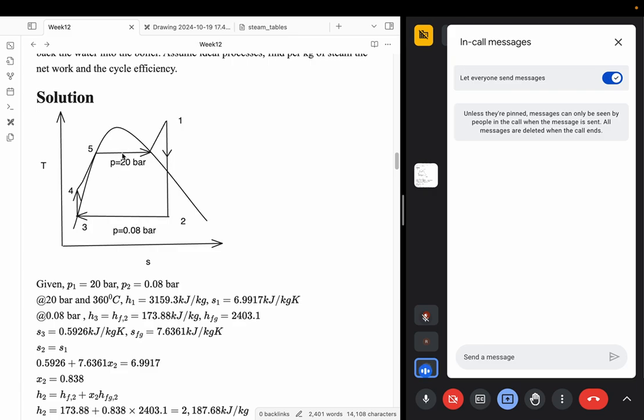But what happens in the Brayton cycle is you are taking air from outside and then some combustion happens because of which heat is added. And then these exhaust gases are expelled out into the atmosphere, right? You're not taking back the exhaust gases and sending them in again. So the exhaust gases to fresh air step is not really happening inside, but you are representing that in your cycle. When you draw the Brayton cycle, you represent that in your figure, but that is not actually happening.